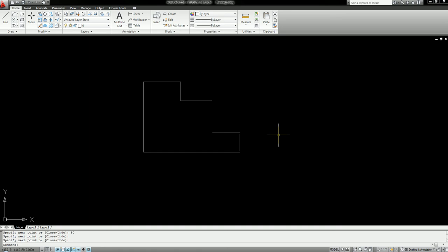and then I can close this object off. Now, I want to put that arc in, so I'm going to use my fillet command. It wants me to select my first object or undo, polyline, radius, trim, multiple. I want to hit R, enter to set the radius, and rather than type in a distance, which is just 50, I can also click these 2 points and it'll make it 50. So now I'm just going to click these 2 lines and it's going to put that arc in. Now I'm ready to begin with the rest of this process and putting in everything else that I need to put in.